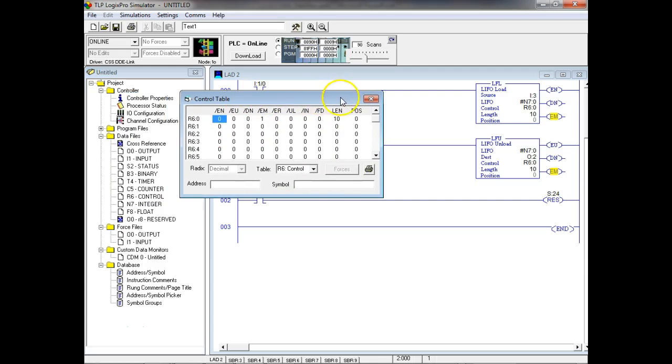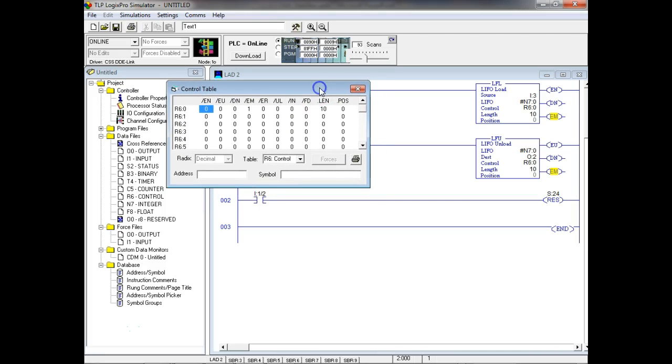here's our bits that we would be using. So EM, where's the EM bit right there? It's set, right? The done bit, it would be set. So this is basically the status register, but this is not the status register that's in the microprocessor. This is the status register that we set up for these other instructions.